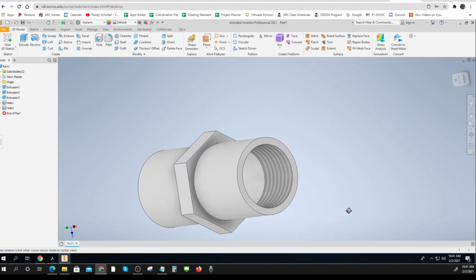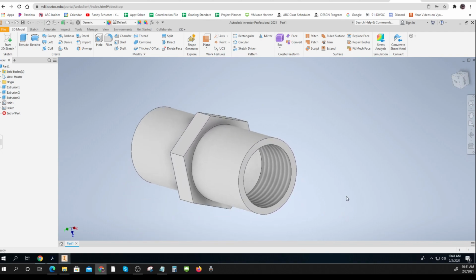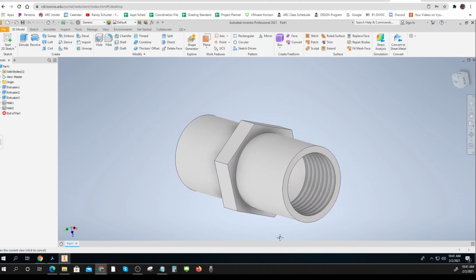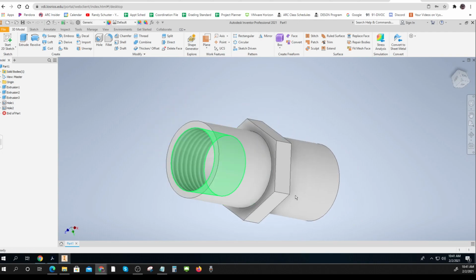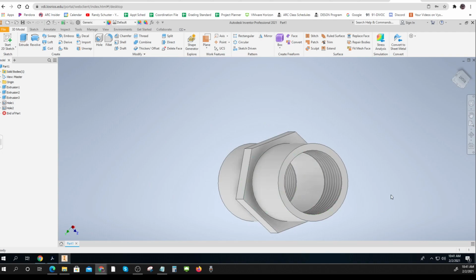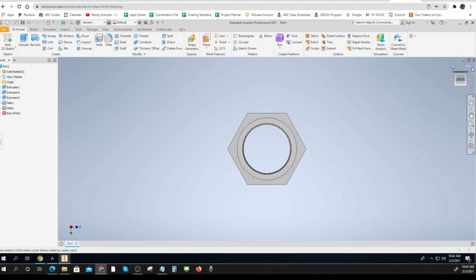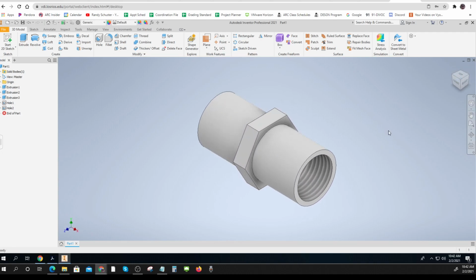I've got it. That's called a base design because I don't care what the dimensions are. I just know there's a hex, a cylinder, and a hole going through it that has an MPT thread on each side. Remember in Design 320 when we worked with primitives and we just said, well, what's this thing kind of? What is it sort of like? That's what I just did. I used the concepts of Design 320. And did I just work with primitives? Yes, I did.